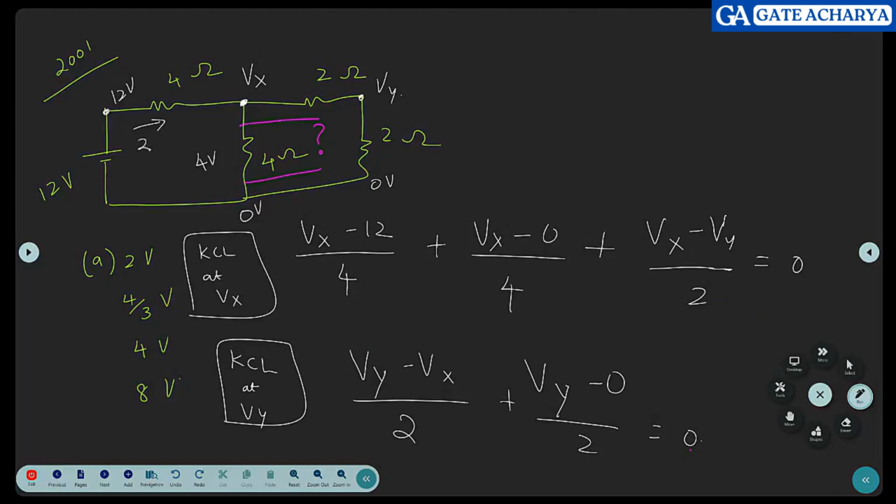2 amps is coming from here, and then you start understanding that it divides between two same resistances. So 1 amp into 4 ohms, it will be 4 volts. So the answer is 4. You don't need KVL, KCL all the time, but in many cases you will.